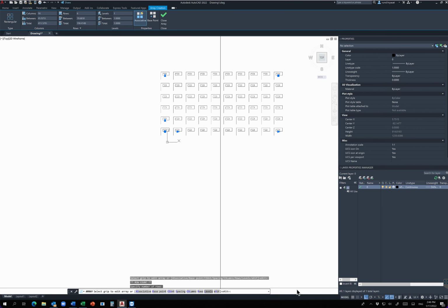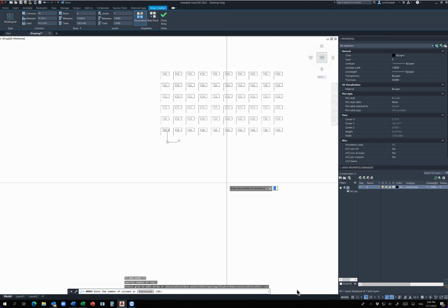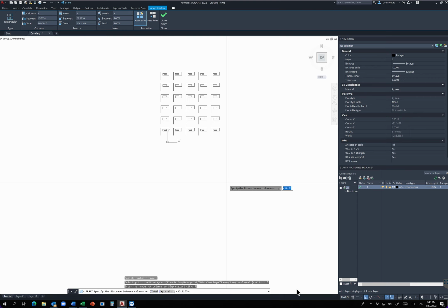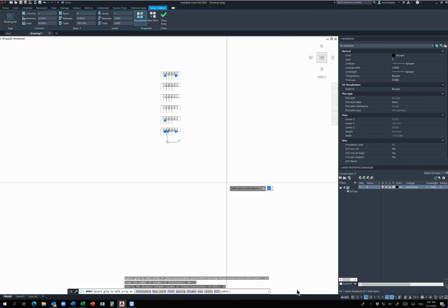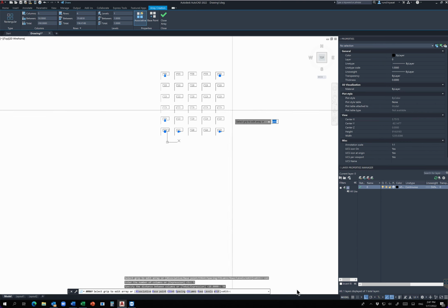Now, alternatively, if I click on COL, as you can see at the bottom, I can start editing the number of columns that I have, and say I want them to be 5 columns, and then the distance between each column and the next is 10. You can see how my objects are too big, so I'm going to change that. I'm going to go back to the column editing mode, and keep it 5 columns. And then I'm going to edit the distance to be 50. You can see how they're getting farther away from each other.